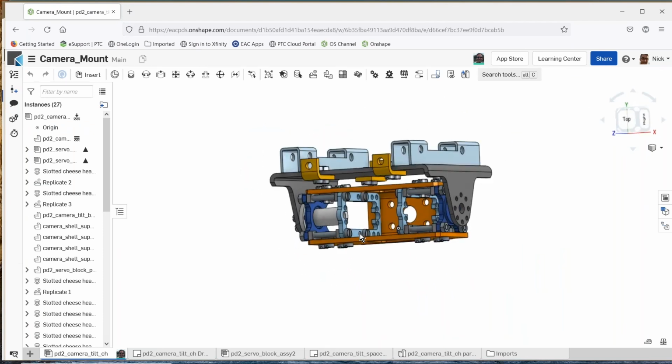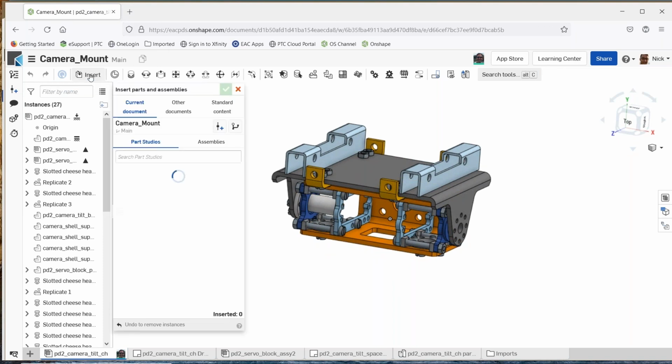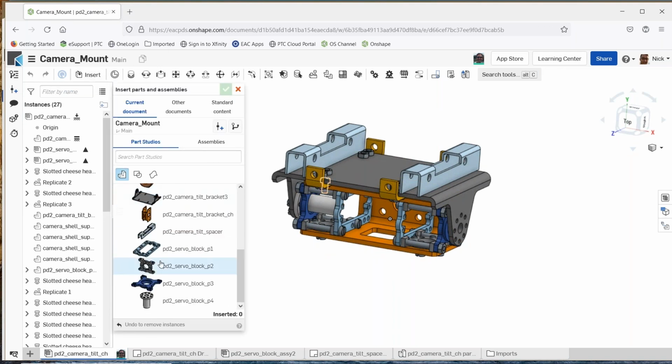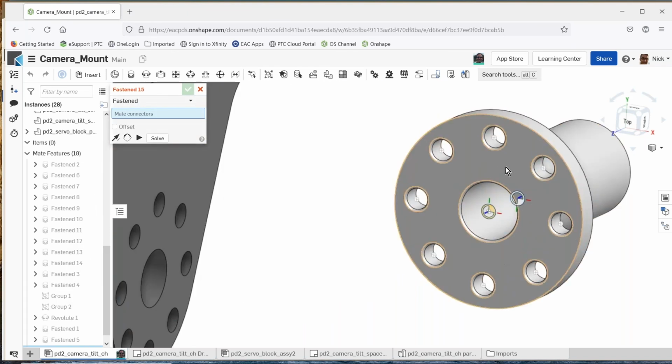So he has to assemble in this other component here. So we'll see a little bit about how assemblies work in Onshape. We can browse down here and find the part that we need. We'll just place it over here. And so now we can start using these different commands up here. Onshape uses something called mates, which I think of as little coordinate systems, but they're flavored to do particular tasks. So we have one that just welds things together, another one that uses a revolute joint or planar joints, or a variety of different things if we wanted to have it articulate.